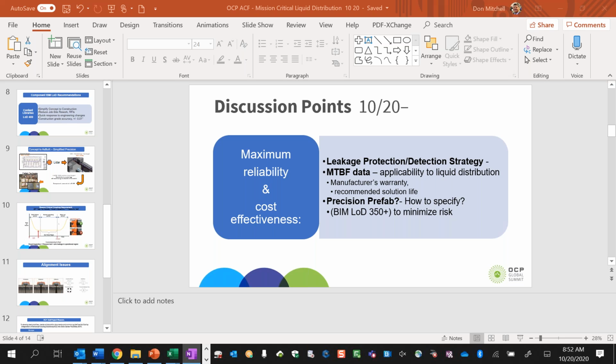The thing we did do from a reliability standpoint was require all of our piping systems, coil systems, and customized designs to be tested at 3 times design pressure at the factory. If they could be sealed, they were sealed with nitrogen gas with valves and gauges on them, so we knew when it was shipped here that it was still tight. Anything that wasn't was repaired and retested. That's how we mitigated our risk: having everything tested at 3 times the design pressure of the device. But would you do that as a hydro test at the site? Well, we did it in the factory.